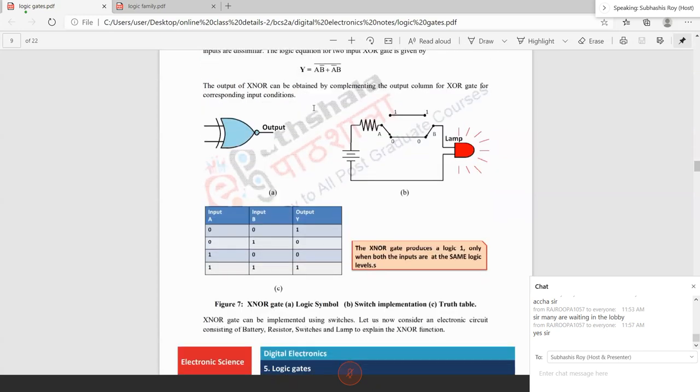In this truth table you will always get a high output when both inputs are the same. So whenever any condition arises where only if both inputs are the same your system should give output, then you have to design an XNOR gate.